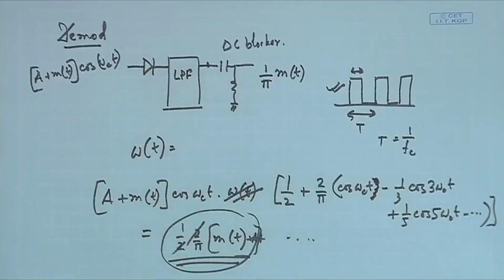So that is what happens whenever we do DSBSC. DSBSC carrier recovery has to be done completely separately. We cannot really employ these things. Whereas if we just add that A term into it, a wonderful thing happens and my receiver becomes very simplified, because in the receiver I just get a diode followed by low pass filtering. That is it, nothing else is required.